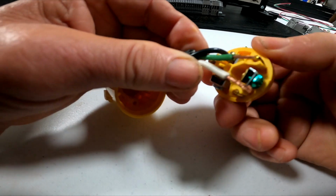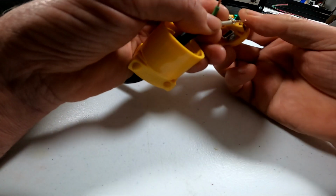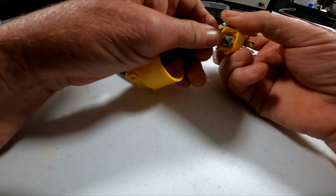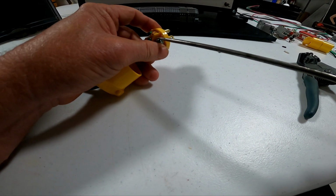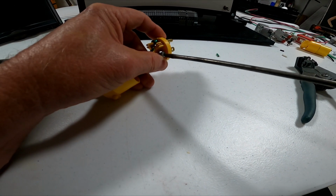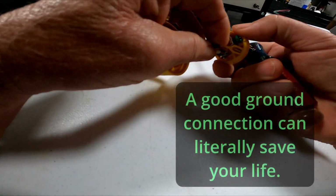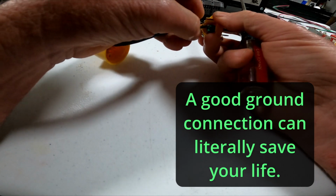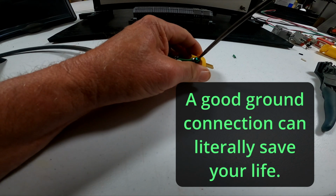Nope, no small wires. Okay, the next one is going to be the white wire, which is the neutral or the AC return line. So that goes to the silver screw. So now we've got the silver, we're going to tighten it up. And now last but not least, we're going to make sure that we get this ground on here. The ground is absolutely essential. The ground is green. So now we're going to tighten up the ground terminal.